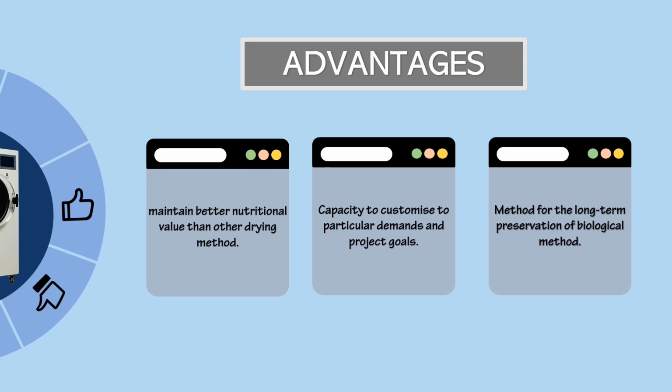The active pharmaceutical ingredient and accompanying excipients will be solubilized in water. The bulk solution is rendered sterile by filtering it through sterilizing grade filters. The sterilized solution will be filled into vials, then loaded into the lyophilizer where the solution is frozen. It will subsequently be heated at very low pressure. According to the literature, the highly porous cake has a low moisture content and can be stored over extended periods of time at the designated storage condition until its intended use.